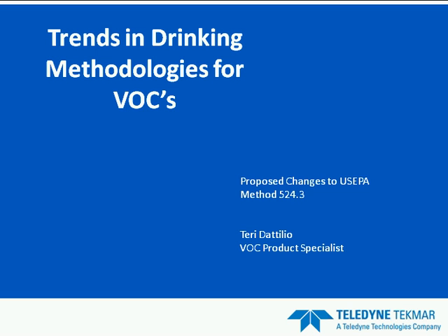They also did some research to evaluate tandem purge and trap concentrators interfacing to a single gas chromatograph. This would help to increase the sample throughput. In 524.2, many of you will know that this is not permitted. They also wanted to revise the current preservation scheme so that it did not include employing hydrochloric acid, which can be a concern in the laboratory setting.